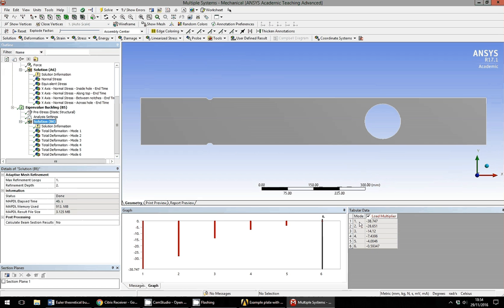So it's all a little bit confusing. So I'm going to put a simple compression load on it to make it more understandable. But it's perfectly correct in terms of we get the same numbers, the same factors. You multiply each of these factors by 560 kilonewtons, you'll get the buckling load. Which suggests that the buckling load is around 0.6 times 560. So 560 by 0.59, about 330 kilonewtons compression is the buckling load.